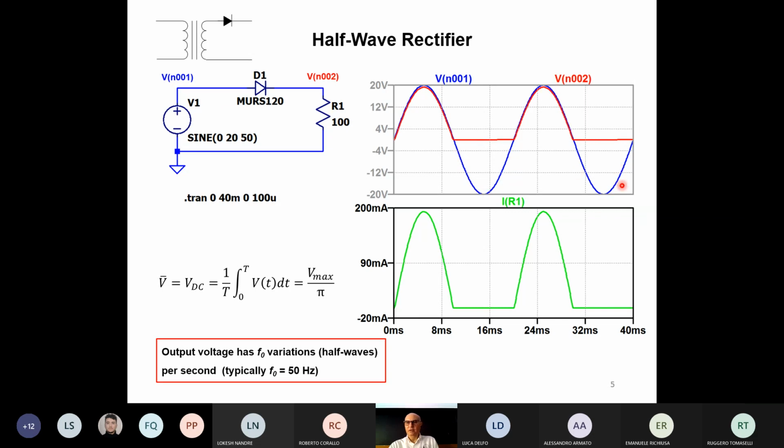It goes up and down. The timing scale, we can take it from the bottom. We have 40 milliseconds for 2 full waves. So 1 full wave is 20 milliseconds, which is 50 hertz. Okay, that's the net frequency.